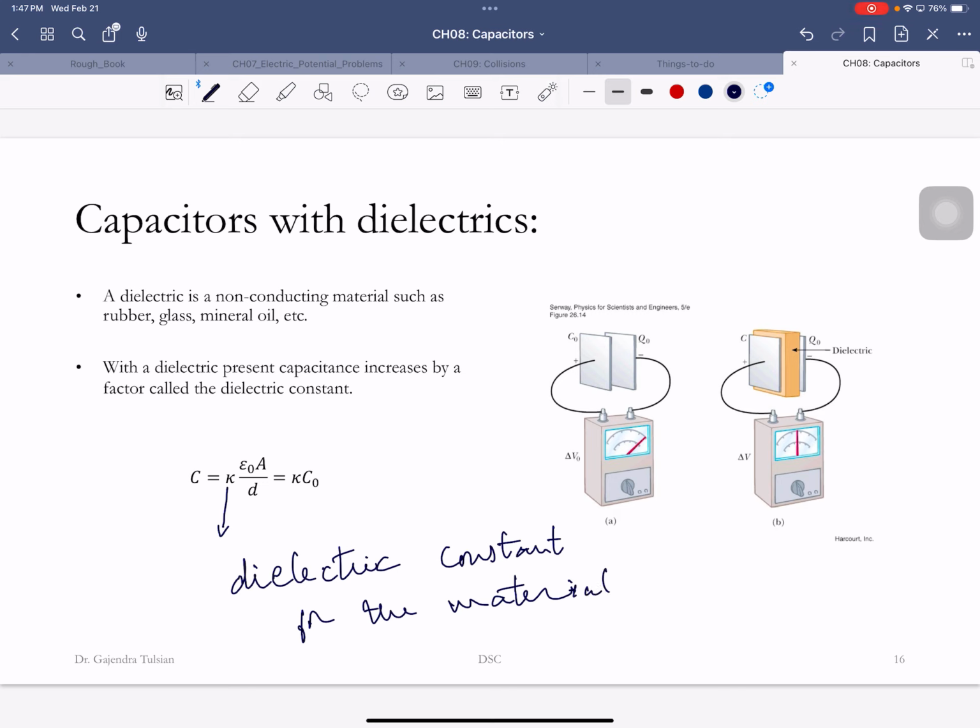Okay, so it's doing several things now. This is preventing the positive and negative charge plates from coming together. It's letting you charge the capacitor to a higher voltage and so on. When you had an air-filled capacitor, there was a maximum voltage you could charge it to. Why? Because you could have lightning there.